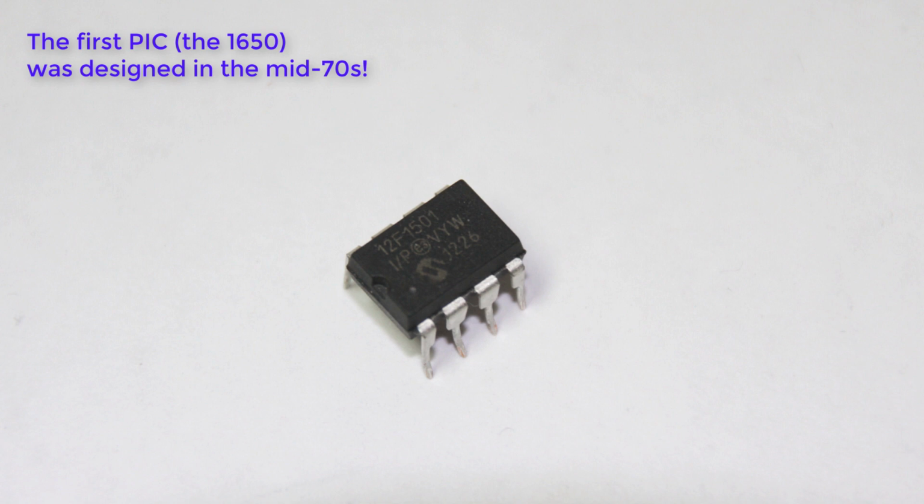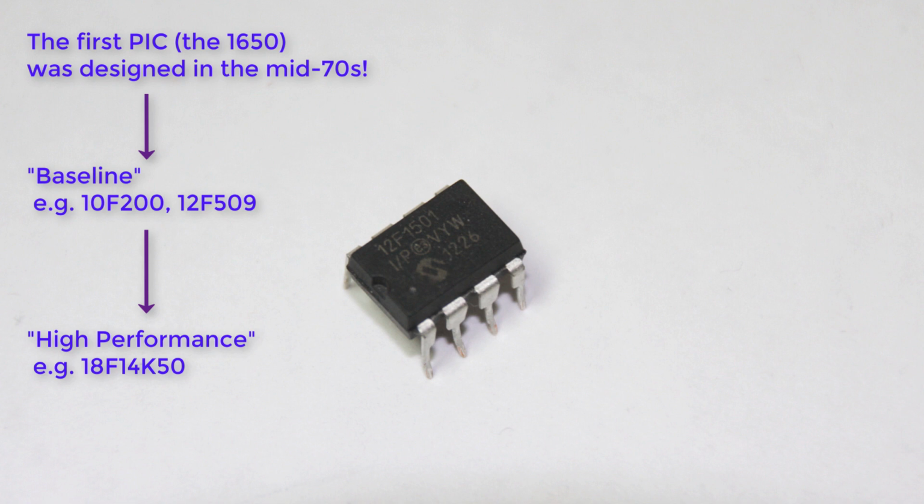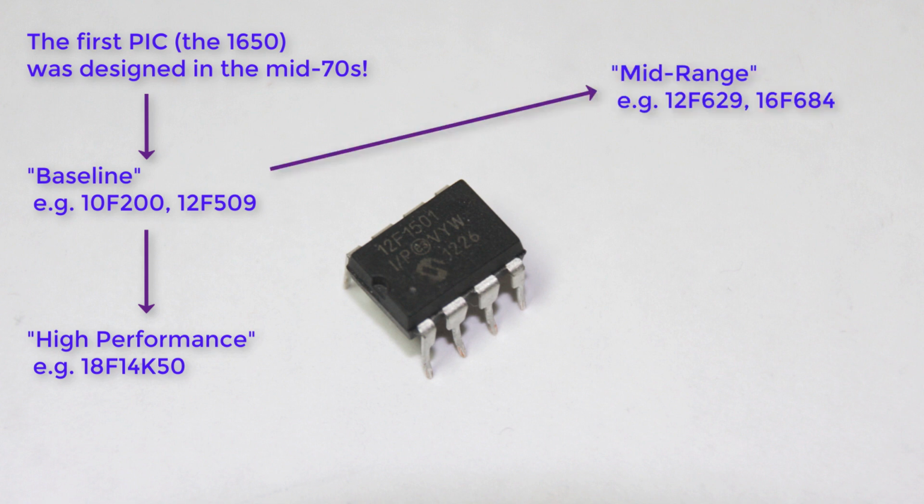At first, Microchip just released new variations on the original design, while the core architecture, the instruction set, the way the chip's organised, remained the same. These days, that original design is called the Baseline PIC architecture. Microchip later developed a higher end architecture, used in the PIC 18 family, and in between was the mid-range architecture, used in PIC 12 and PIC 16 devices.